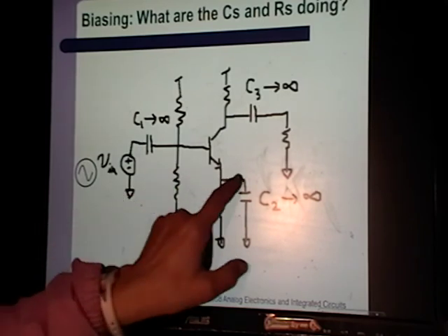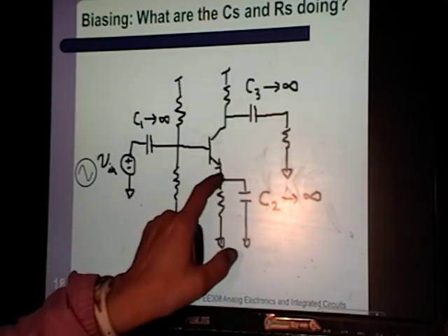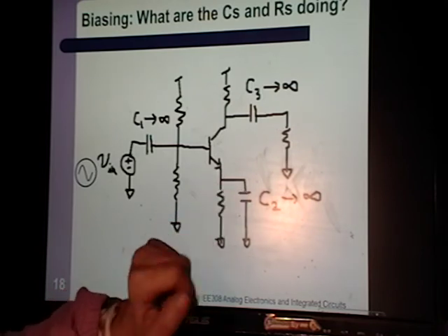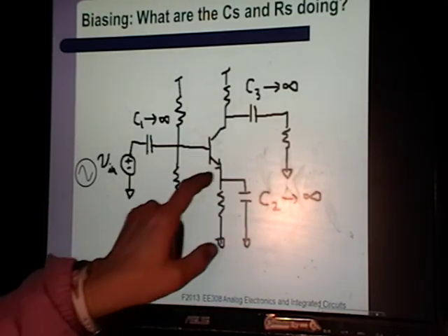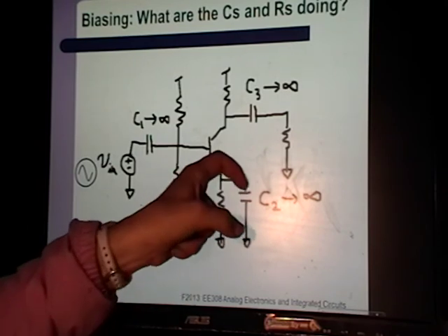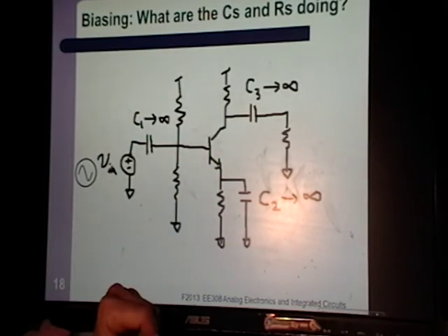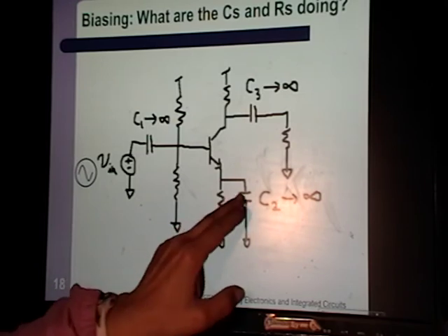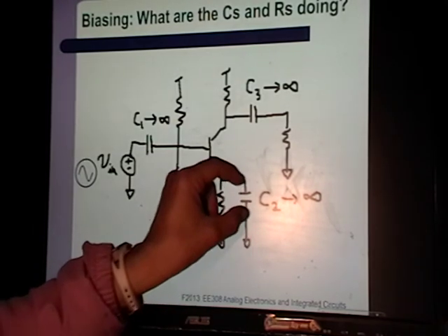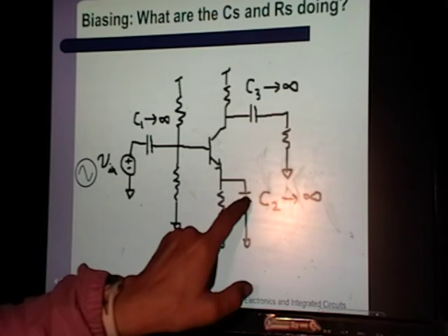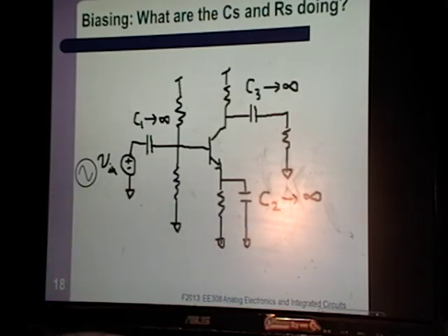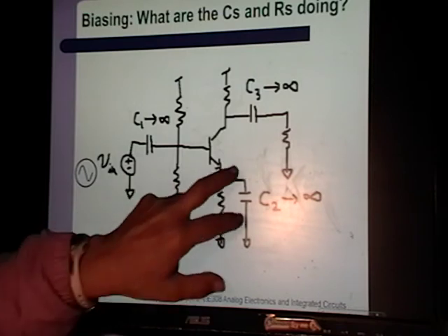So what you do is put a capacitor in parallel, which gives that current an alternate path to go through. If you make this capacitor really big, when you change your current, it's all going to go on and off of that capacitor. It takes a lot of current onto that capacitor to change the voltage. So if you make a big capacitor, a lot of current has to go on there before the voltage changes. If the voltage changes across here, yes, a little bit of current will go through here, but the majority will go onto this capacitor. It's like you have to fill up that lake before the voltage goes up.